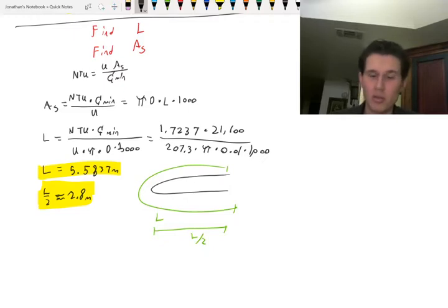We would want to do some more iterations. We also want to keep in mind some things when we find this out. Our convection coefficients, they can be off by 10%, they could be off by 25%. So it's not certain. Some of our NTU approximations, depending on how the inside of the heat exchanger is built, it may not be exactly how we calculated it.